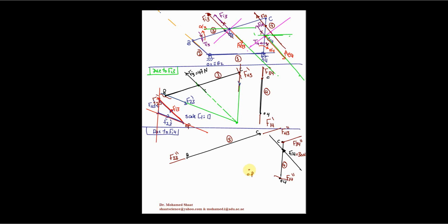So from this point O4, I'm just gonna mark a point and draw a line with a length of 3 centimeters, which is equivalent to 30 millimeters. The end of this line should give us the force F. This force should be the Fi4. Make sense? Then you're gonna draw one line from one end and another line from the other end.